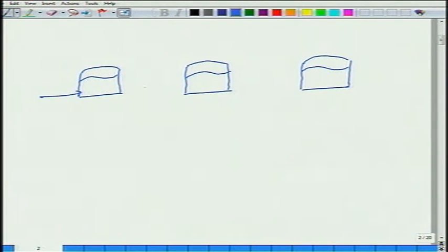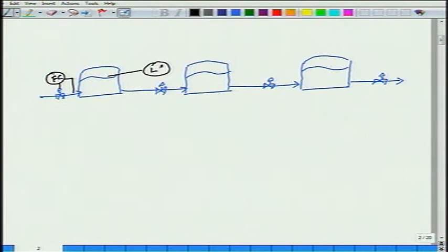And it is just a simple tanks in series. All right, you got all these valves. In the absence of any other information, I decided, like a simple minded chemical engineer, okay, this will be my throughput manipulator, in which case the level control would be this way.